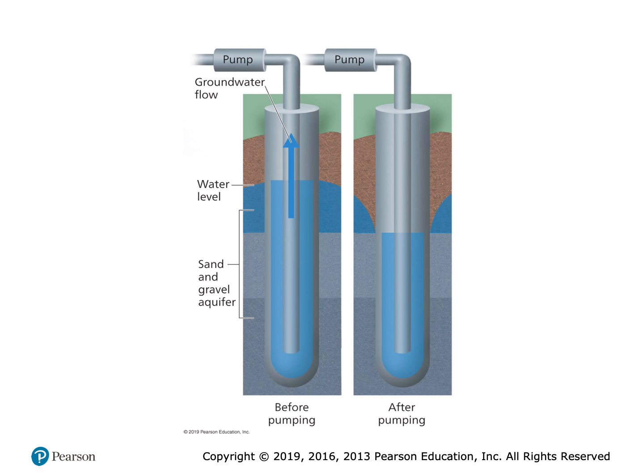This is a look at how water is pumped up and out from the aquifer itself. And you can see how before pumping and after pumping, the level of water changes in the pump. When pumping ceases, the water table recovers, and the rate of recovery depends on the permeability of the aquifer rocks and sediments, how quickly more water can get down there.